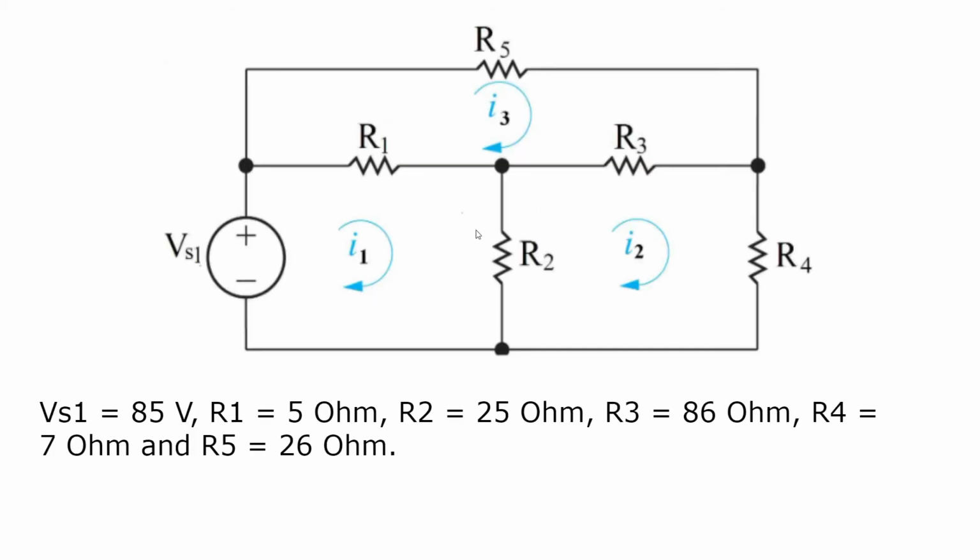So this example just came from homework 2. Our unknowns are I1, I2, I3. This is a mesh analysis problem, so our unknowns are currents. And our equations come from taking the loop, and across the entire loop, the sum of the voltages is 0. So our resistances and this voltage are given. Those are our givens, and we're searching for these currents.